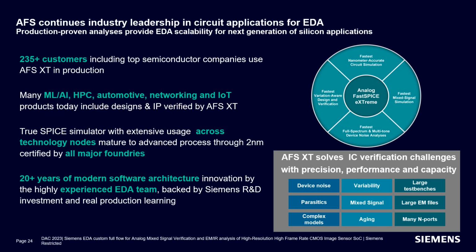This is a brief summary about AFS. So as we all know, AFS continues industry leadership in circuit applications for EDA. So AFS XT solves IC verification challenges with precision, performance, and capacity. We can do all different types of analysis, including device noise characterization, parasitic simulations, device aging, mixed signal simulations. AFS is able to handle large test benches, large EM files, and can deliver performance at capacity.